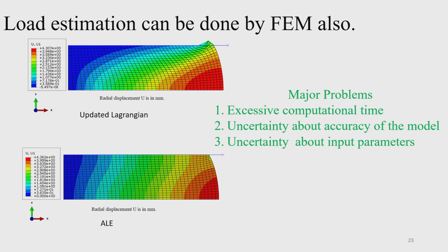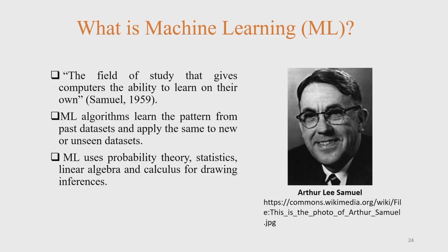Sometimes you get this type of thing, suppose during forging, and you do not know whether it is due to numerical errors or whether the process physically shows this type of behavior. See, when I used updated Lagrangian, I got this type of thing, but when I used Eulerian, I did not get this type of bump there.